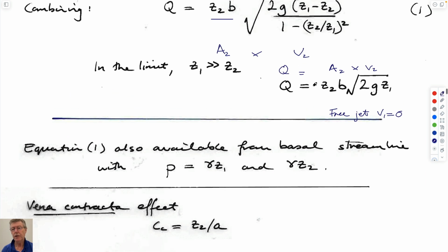So in other words, we multiply this through by some correction, which should be non-dimensional because we know that this is in units of meters cubed per time. This also is in meters cubed per time. So any correction has to be dimensionless, and this would typically be reducing the flow, between 0 and 1.